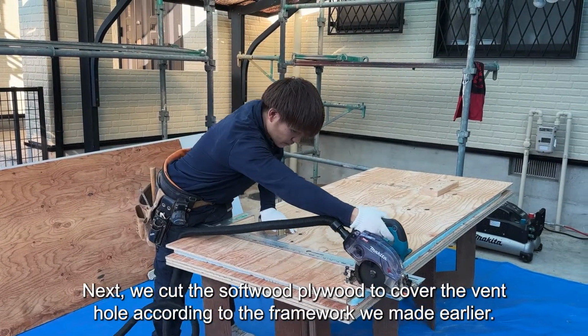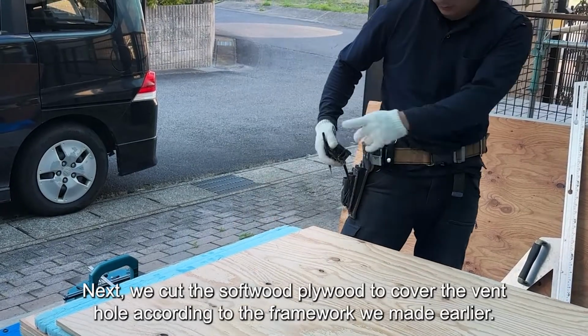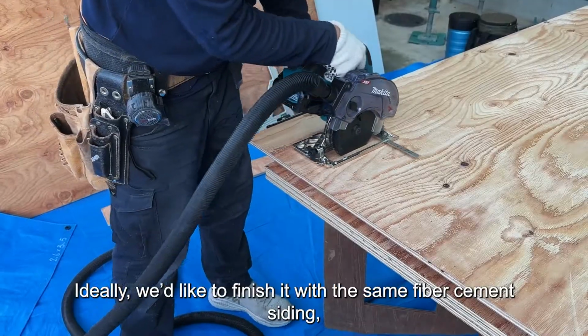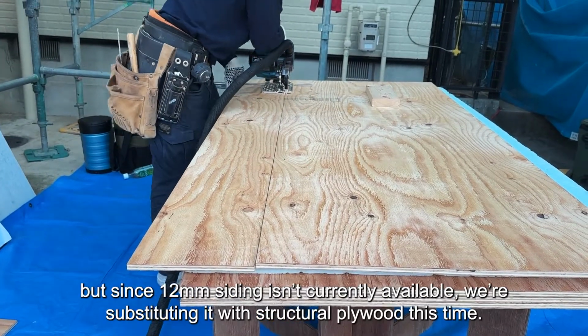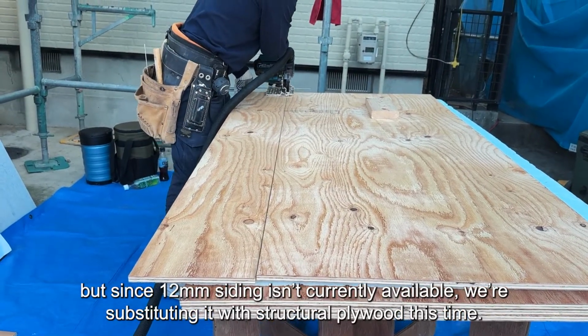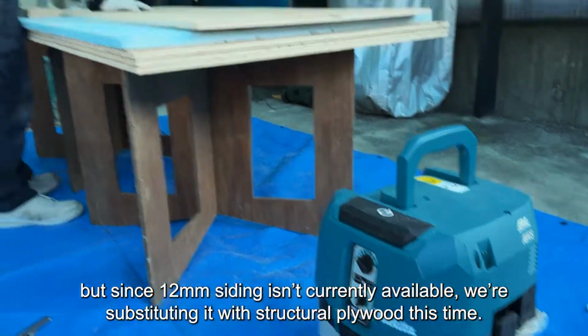Next, we cut the softwood plywood to cover the vent hole according to the framework we made earlier. Ideally, we'd like to finish it with the same fiber cement siding. But since 12mm siding isn't currently available, we're substituting it with structural plywood this time.